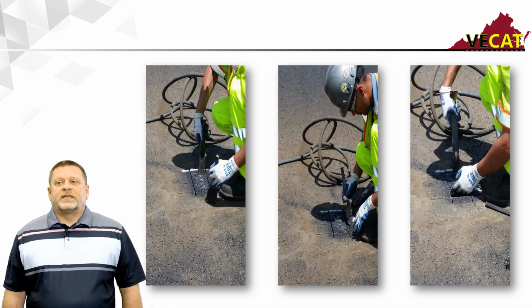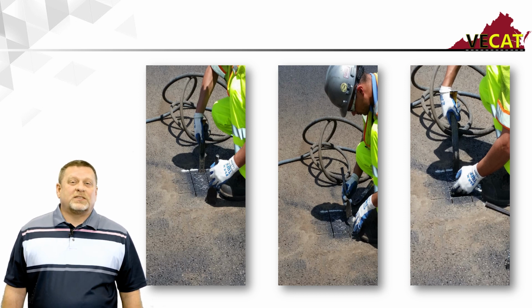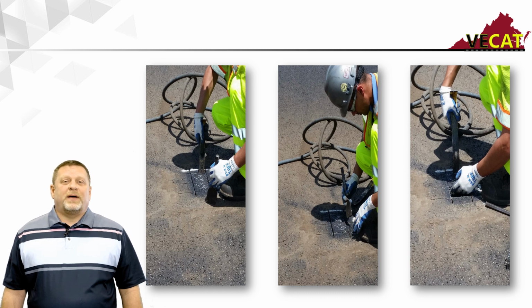Now you see the technician, he's beginning to remove these specimens. It's recommended that you use a rather wide spatula to do the prying. Basically, you stick it in a slot you cut and you just pry back and forth until it breaks free from the pavement below.